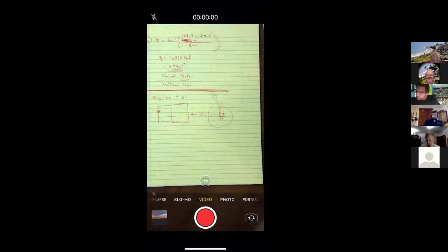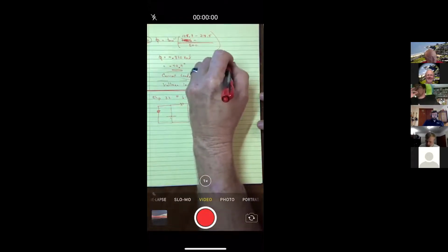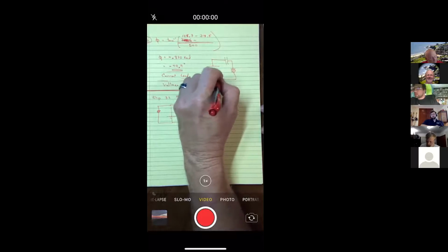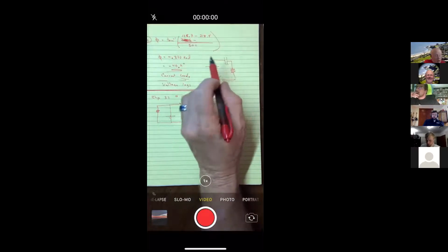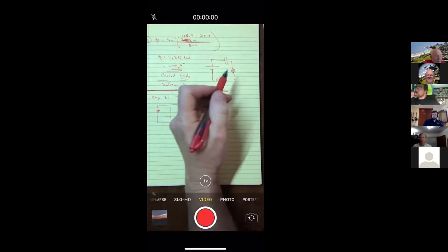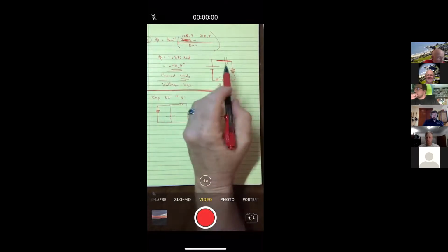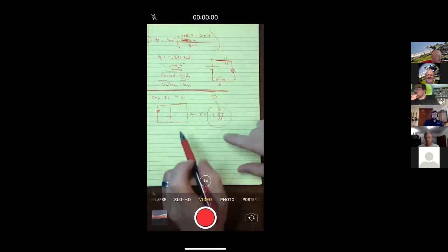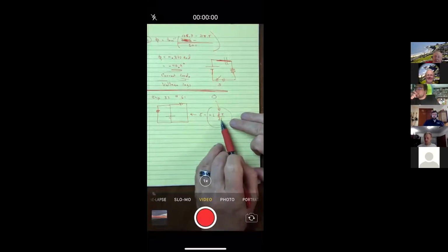It's kind of the reverse of what we did with capacitors. When we had a circuit like maybe this, where we had a capacitor, I should have put a switch in here. When you first close the switch, there's no charge on the capacitor yet. And with no charge, there'd be no voltage. And so you can just replace the capacitor in your mind for that moment. You can say it is just a wire. So right when we closed the switch, we treated the capacitor as a wire. And I'm saying the reverse for the inductor. For the inductor, you can treat it as a wire after a long period of time.